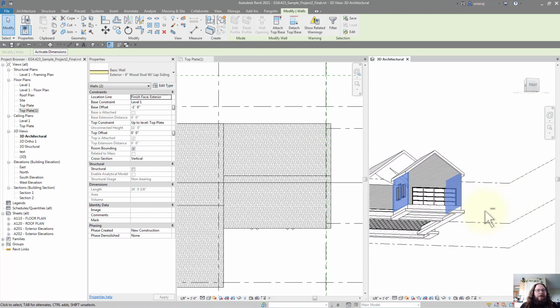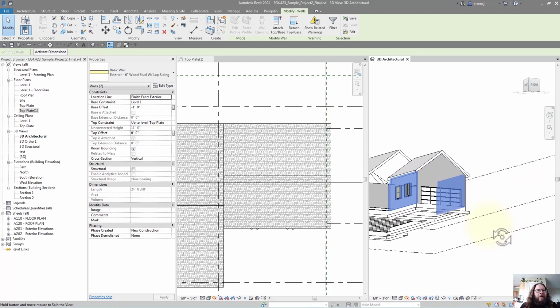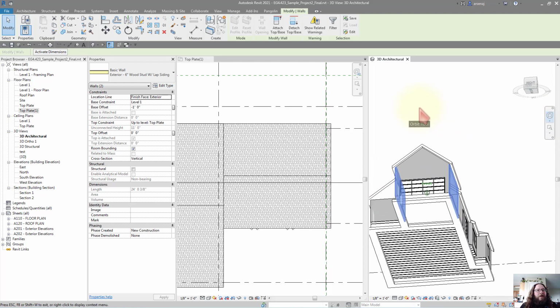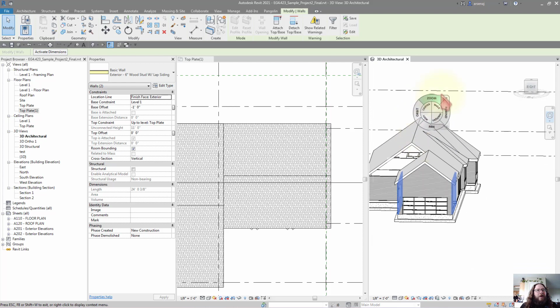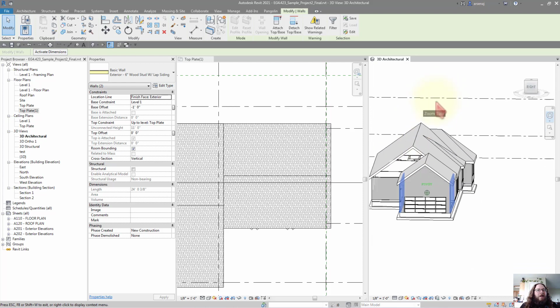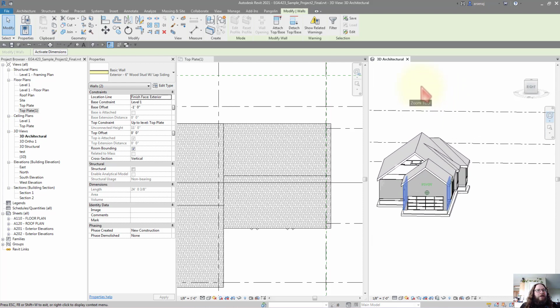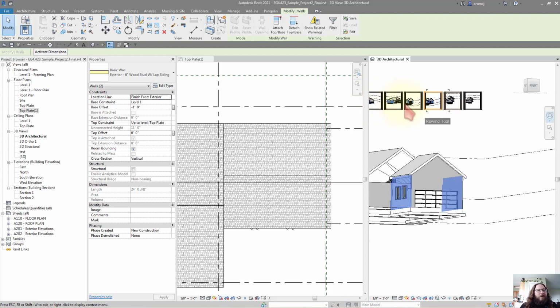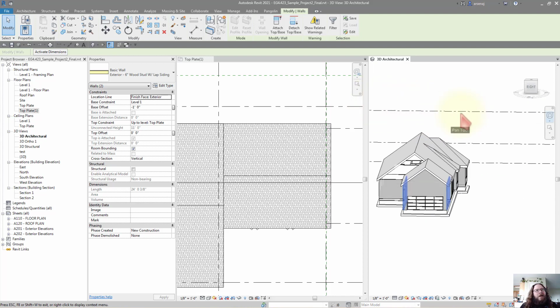You can see if we pan around, hold shift and middle mouse click, and we'll pan around. Or if you watch the other navigating 3D views, you can use this scroll wheel to then orbit by clicking the different parts on the scroll wheel to move in and out. You can actually rewind, so if you liked a view from before, you can kind of go back.